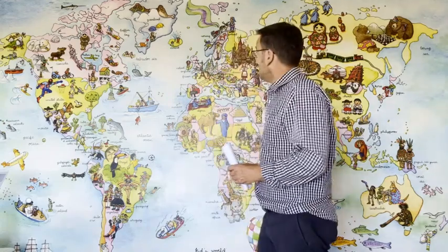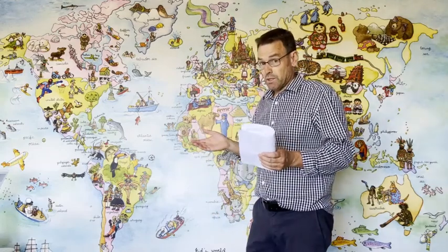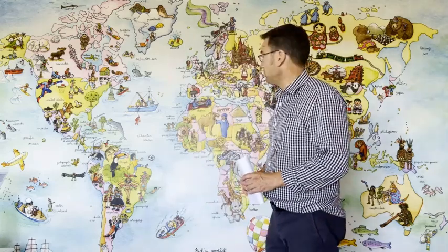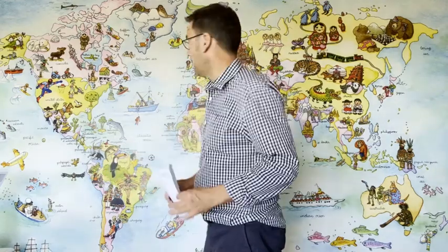The United Kingdom, for example, they've created their own transverse Mercator projection, centered around 2 degrees longitude, not 3 degrees as the UTM projections are. And they've adopted a scale factor of 1 at the center, which means pretty much that developed cylinder is sitting just on the surface, not below it, if you think back to Andre's diagram. What that means is the distortion around the United Kingdom from that projection is minimised for the size of that